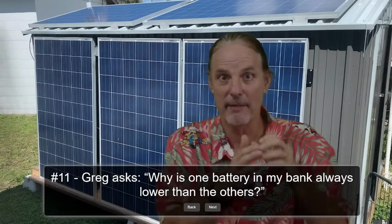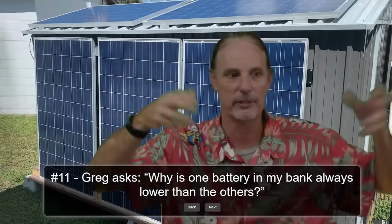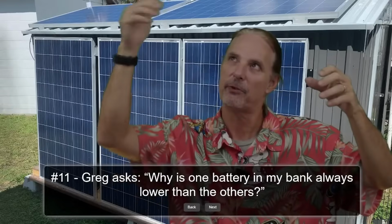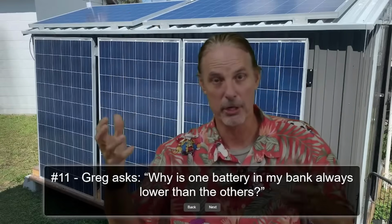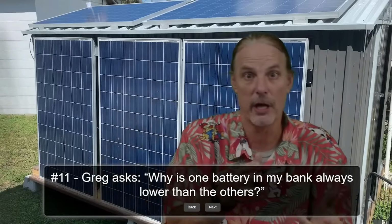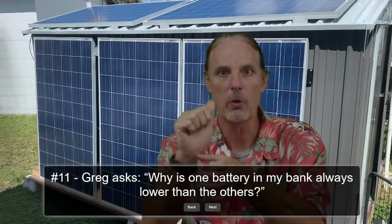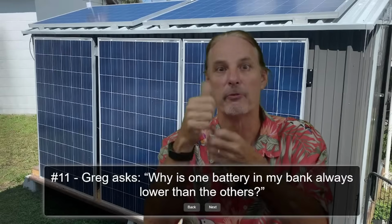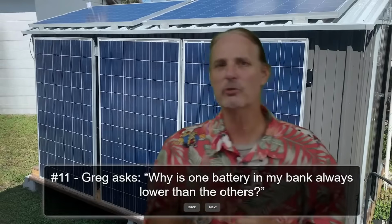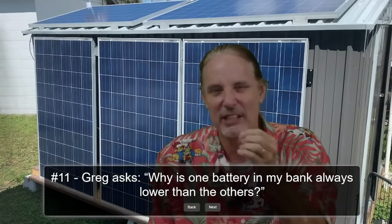if you don't have that kind of measurement to make sure that water jug is full, and keep in mind, getting back to the original question of why is one lower than the other, every battery you have is going to have a different amount of sun pointing at it and a different amount of evaporation. Every battery has a different nozzle with different washers. One may leak more than the other. Every battery is going to start pulling a little sooner, before it's even measurable by whoever is calculating how much goes into it. So this is what's important for you to understand, that there is no exact science here.